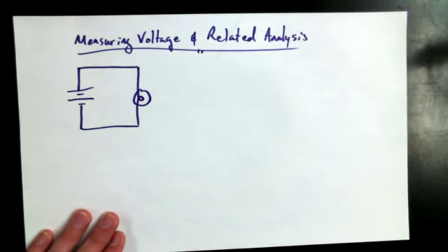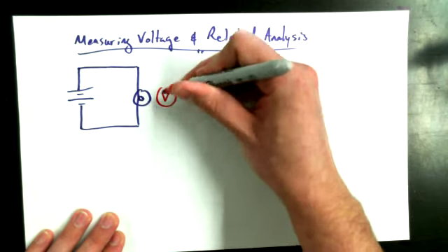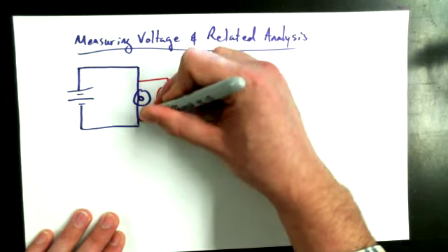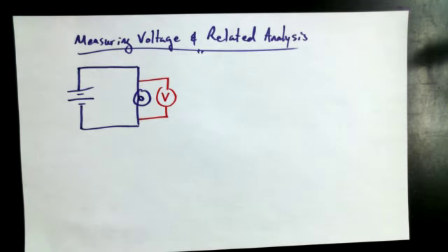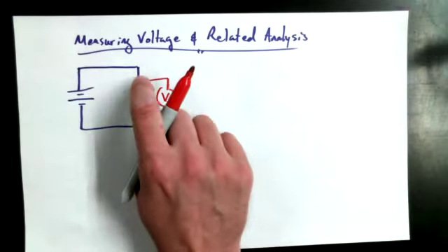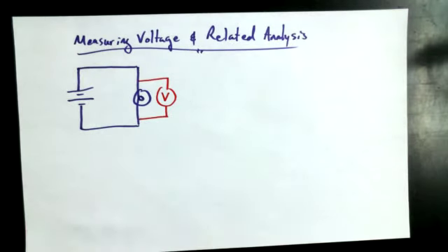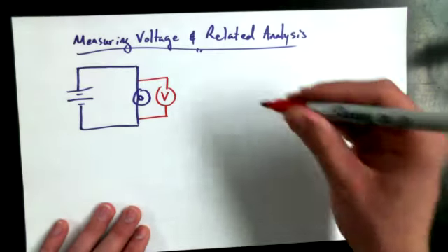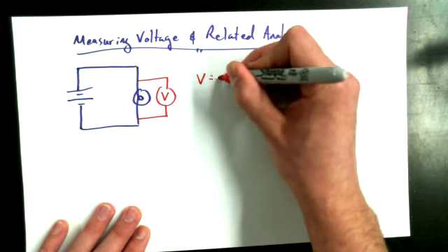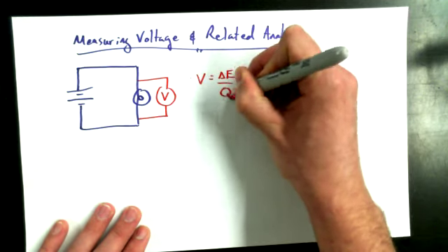And you told me before, how do you connect a voltmeter? Series or parallel? Series. A voltmeter. It was a 50-50 shot, guys. In parallel, because what we're effectively doing is finding a difference in electric potential energy, and that's why they call it potential difference. That's the delta E, the difference part, and the electric potential is the E over Q part. So we're finding the electric potential difference between the energy per charge on one side compared to the other side. It's really a comparison, subtraction, right? In any case, we're finding the voltage. We know that if we're finding voltage, we're finding change in energy per charge.